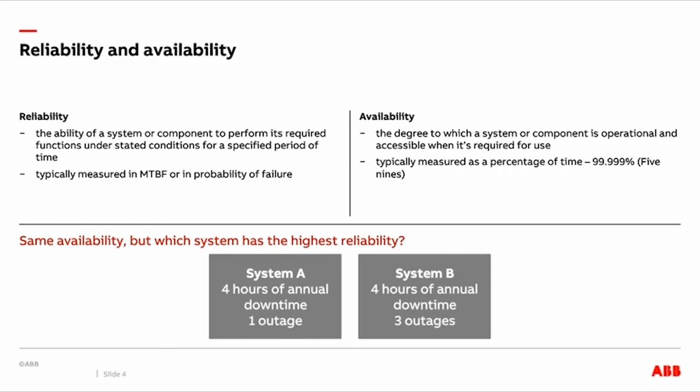Reliability can be a better tool in assessing a data center design since reliability gives better granularity. Large increases in reliability as measured in probability of failure yield very small increases in availability. Therefore, it is easier to measure the cost-benefit and design changes using reliability rather than availability.